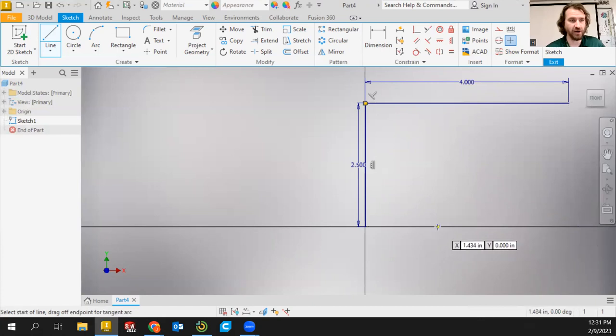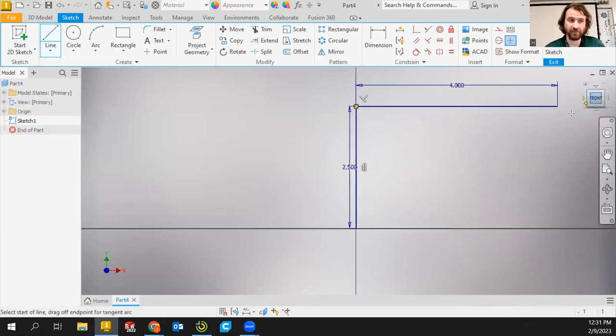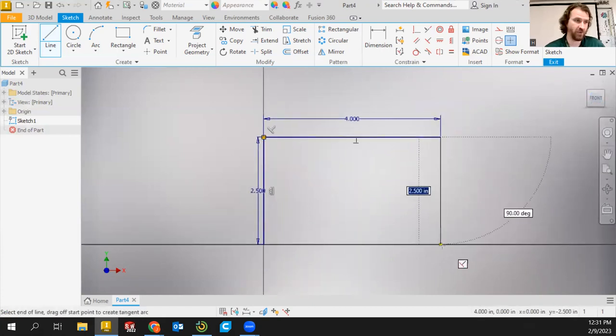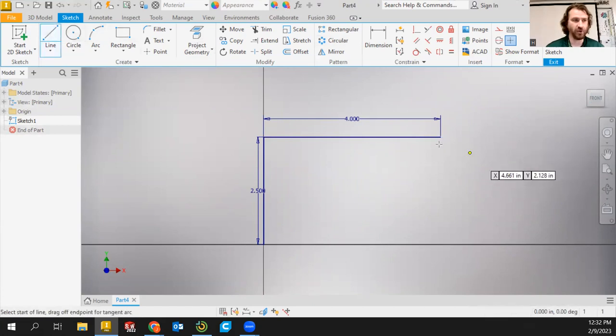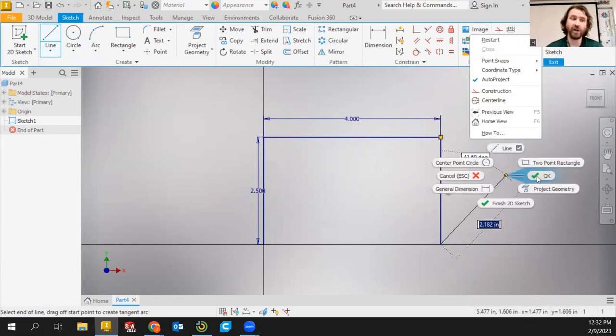So I can hit enter here, but it didn't do anything because I didn't type it, right? You need to make sure, again, I could click or I could hit enter. If I hit enter, it's not going to do it as I'm coming down. You see there's a weird situation here with the line tool. If you're coming off of a line and you hit enter without actually typing in 2.5, no, it said 2.5. It said it was there. If I hit enter on the keyboard, it's not going to create it. If I click with the mouse, it will.